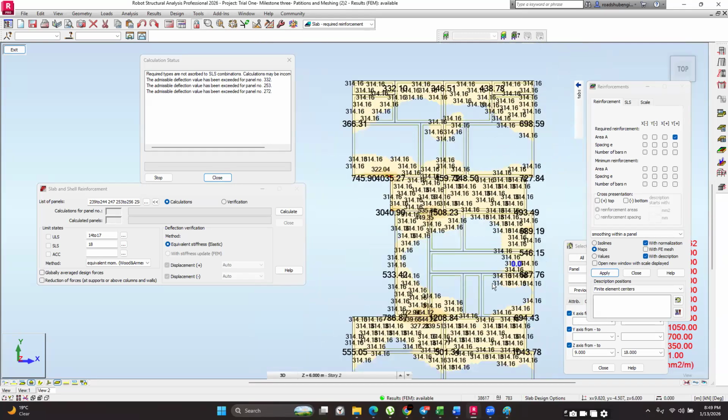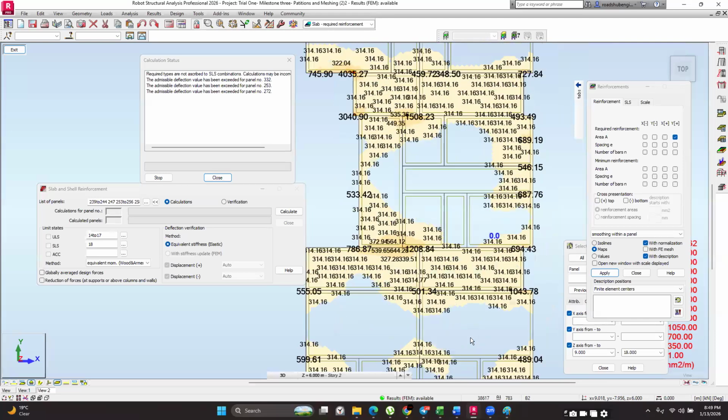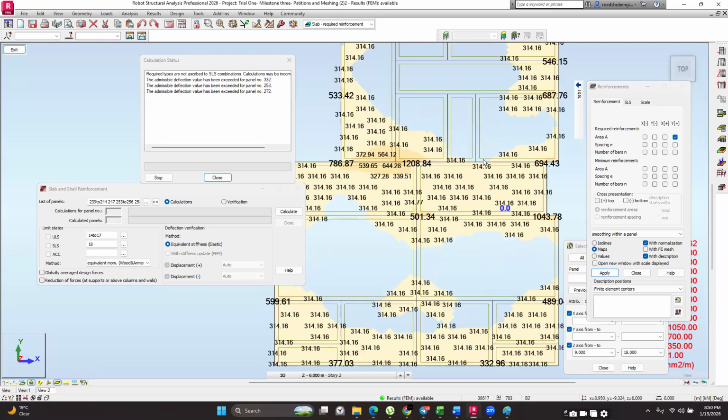So the thing I like about using this method is it is a really good way of guiding you on how to detail. Okay. So when you want to detail your structure and to do your detailed drawings, you would need to know where you have your top bars going in certain directions. So someone may look at your detail and wonder why you have top bars over this entire panel. It might not make sense to them, but for you, you're going to be knowing that at this particular section over here, you had hogging moments, and that's why you have these areas here.